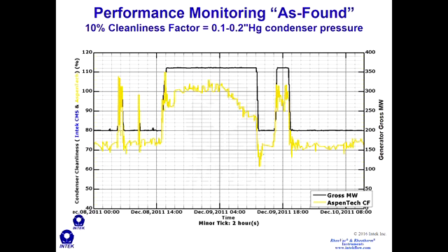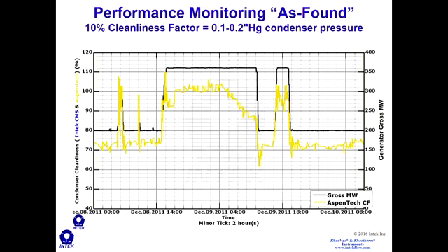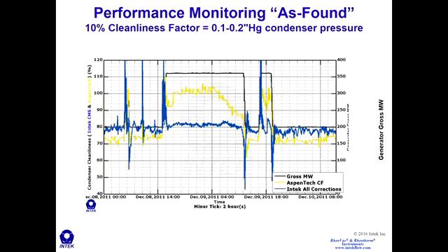And so when I did that, we took the test grade measurements, and when I recalculated condenser performance, this is what I got. So this is the same time period. So there's the cleanliness using station equipment measurements. Now here's the cleanliness using test grade measurements. Okay, and the cleanliness is pretty much stationary throughout this time period. Now it changes on these transitions.